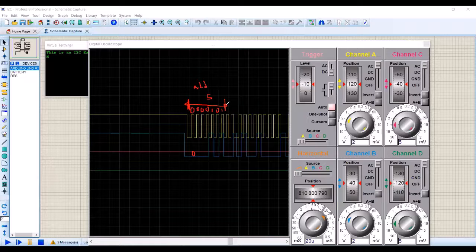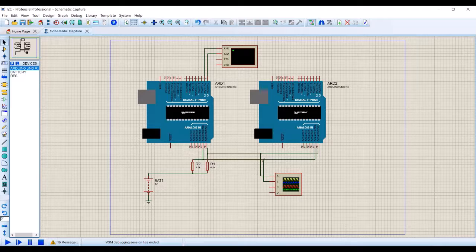Then we have this read write command. So writing is 0 always. Yeah. So likewise, you can then send in the data again and like that. So you can debug using the oscilloscope if the data packets are sent or not. So the same thing is applied if you're working in real life. You can hook up an oscilloscope, and if your system does not work, this is how you're going to debug.